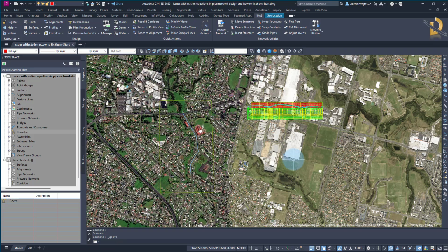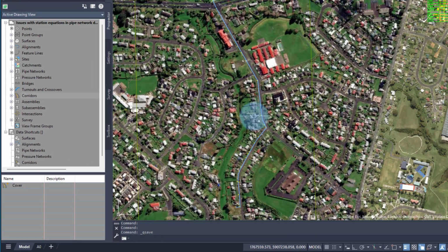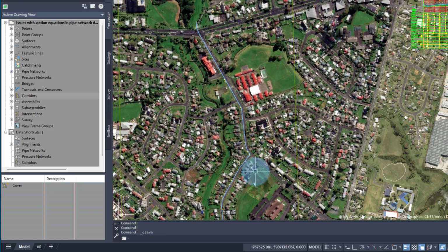In this case, let's say I provided drawings to the construction site, but now I need to introduce some changes to horizontal alignment. If I do any changes to horizontal alignment, it will have an impact on the chainage values further down up to the end of the alignment. And I don't want that. So I only want the chainage values to be changed up to the end of the changes I'm going to introduce. And from there, I want the chainage to be the same as it was before.